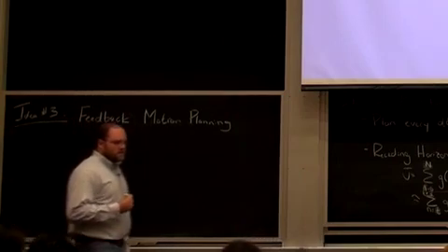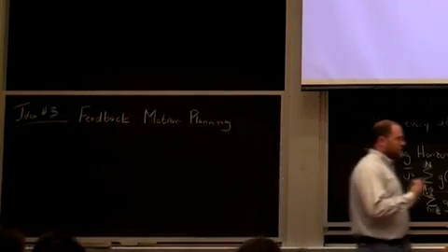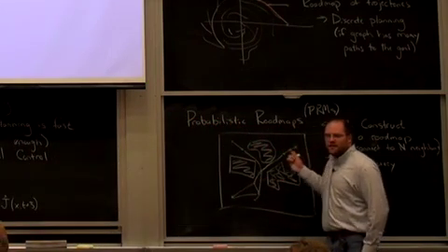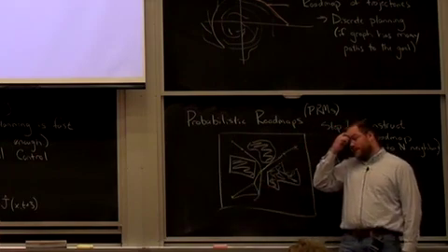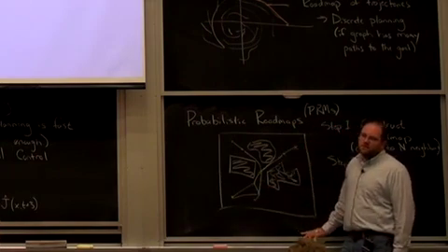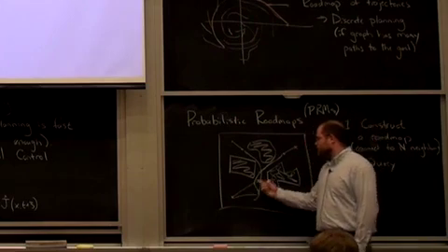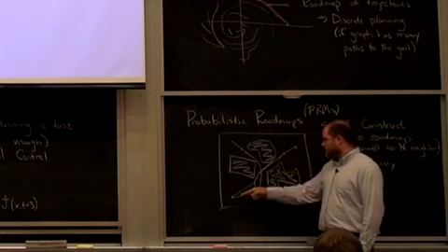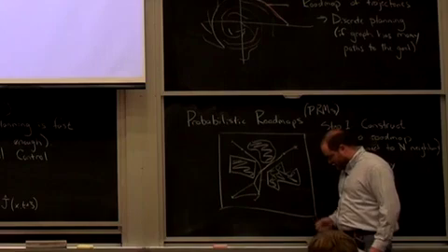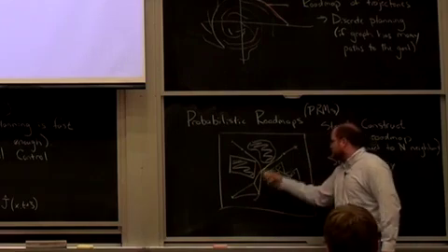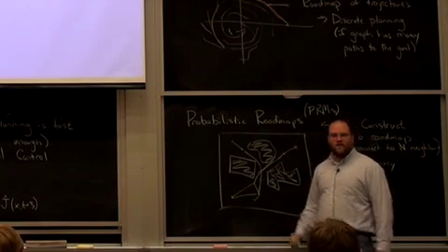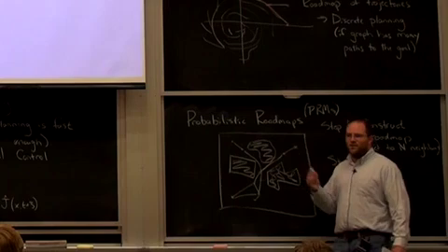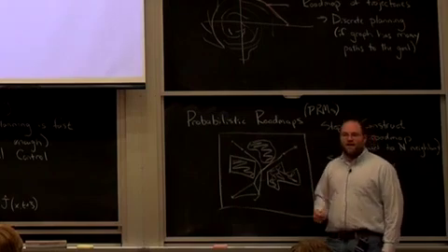So far we've talked about building some trajectory that we thought was good, and then afterwards going through and stabilizing it with feedback, right? That's not always the best recipe, because you could imagine, for instance, designing a controller that locally looked very good, but was completely unstabilizable. I say, perfect, my first stage of control design, pick this trajectory, now I'm going to run LTV LQR on it to stabilize it, and then I find out, whoops, right there it's not controllable or something. My cost-to-go function blows up.